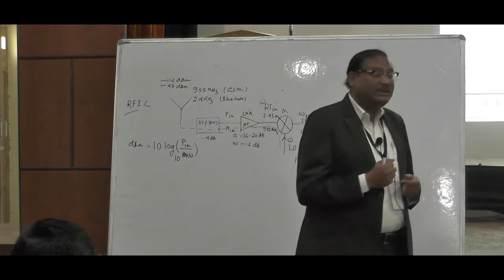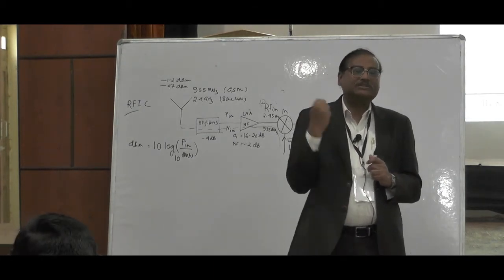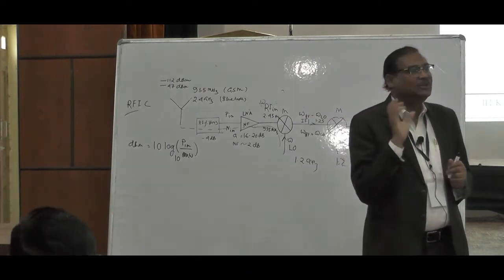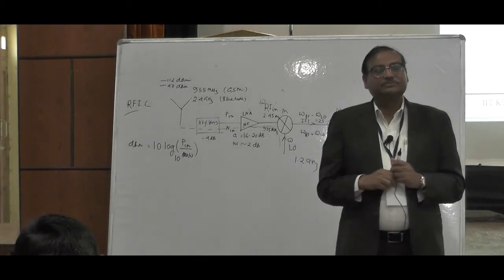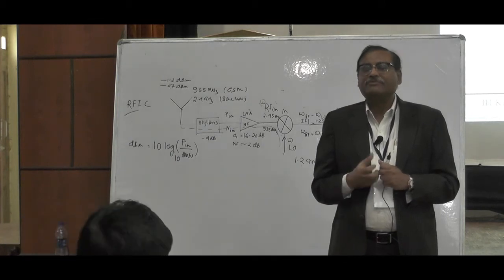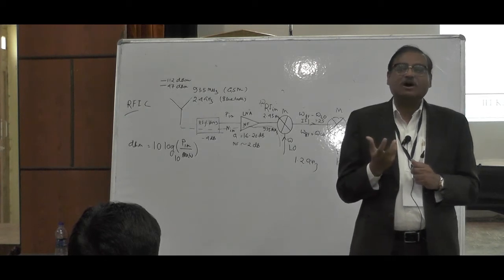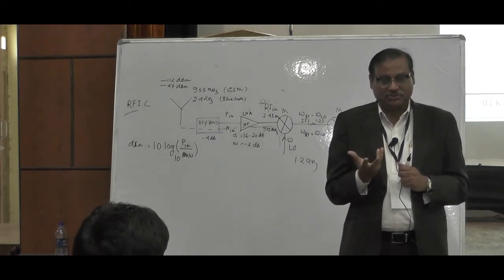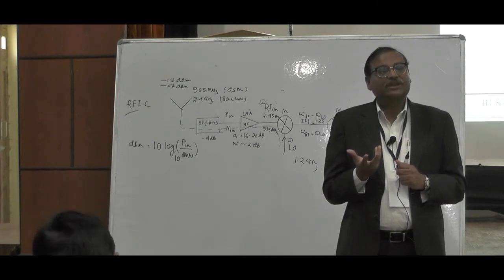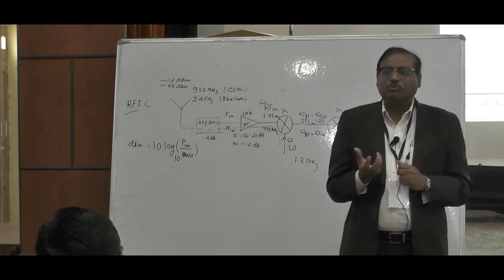And what are the challenges in implementing this in RF CMOS? While you are implementing all your transceivers inside the silicon, the main challenge is not the active circuits but the passive circuits. Those inductors, capacitors, and transformers have a very low quality factor. What is quality factor? It actually tells you how much power is being lost. That is its efficiency. The quality factor of an inductor, for example, is very low, around 3 to 4.